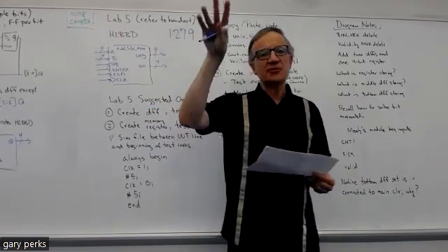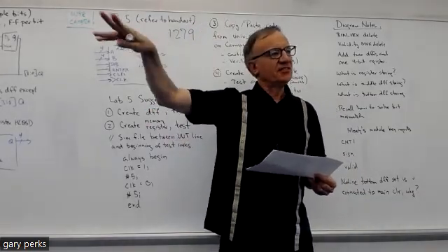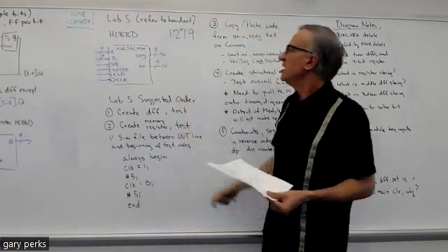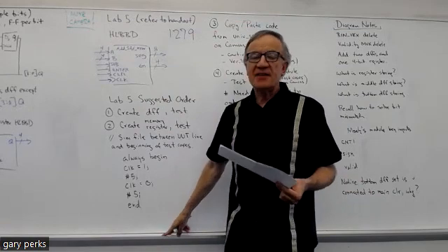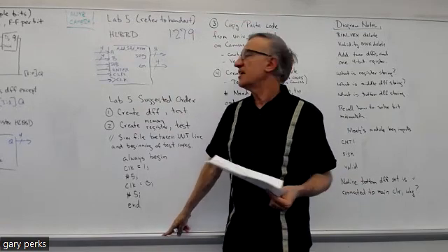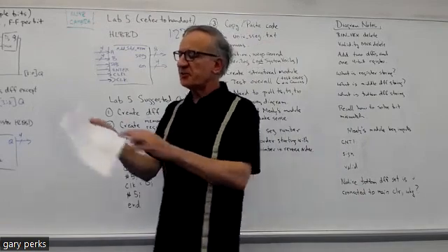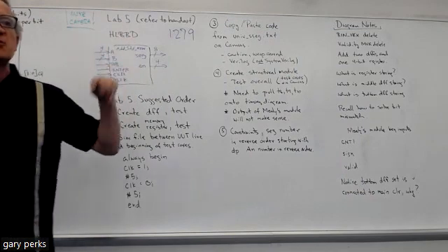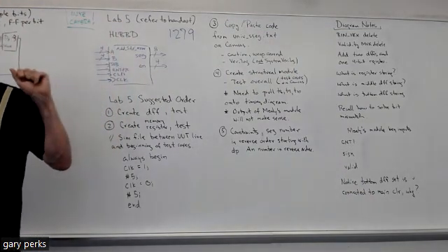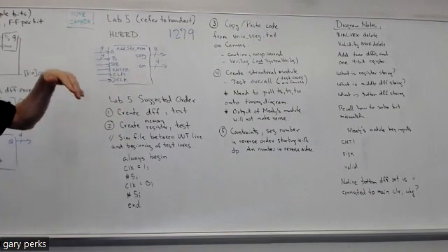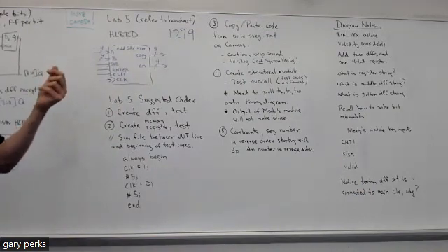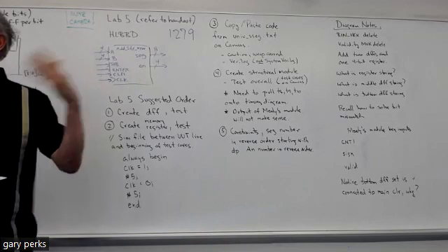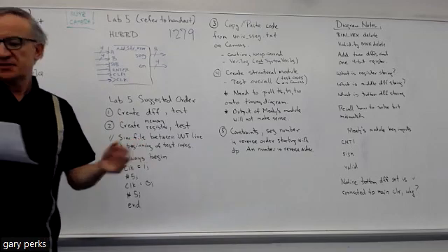Because remember, an is what's controlling whether the display is on or off, and there's 4 of them on the Basys board. So an is always going to be 4 bits. The reason why seg is 8 bits for Lab 5 and not 7 like in Lab 4 is because Mealy's module, the time multiplexer, uses the decimal point. So the decimal point is the added seg. You might have noticed in the constraints file where the segs are that one of them is labeled DP for decimal point. So that's being used by Mealy's module.